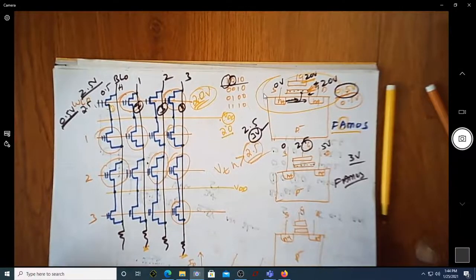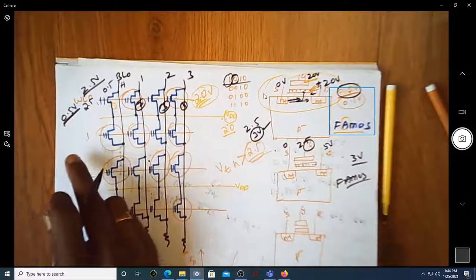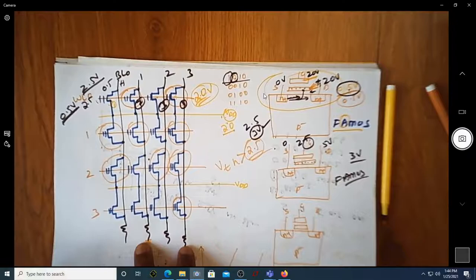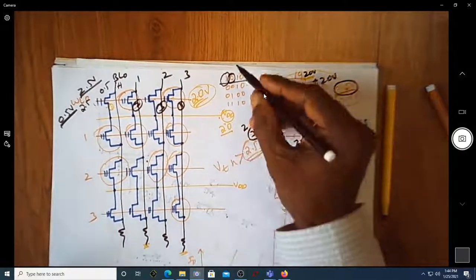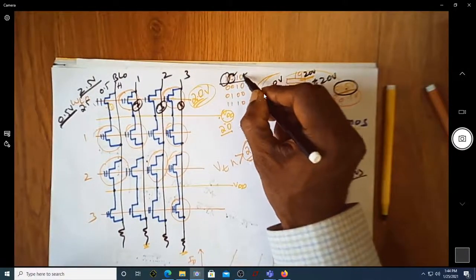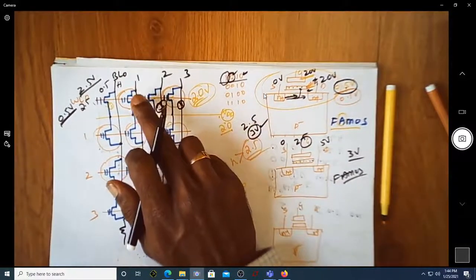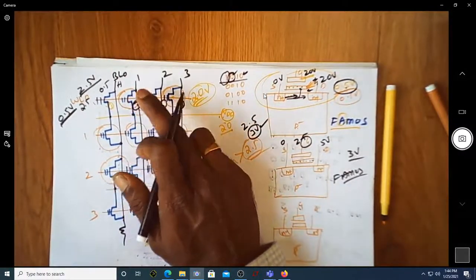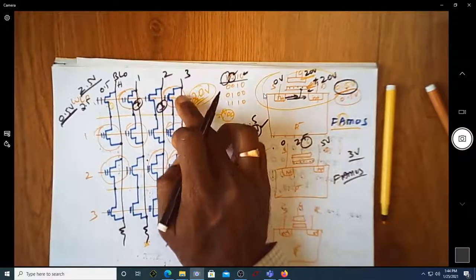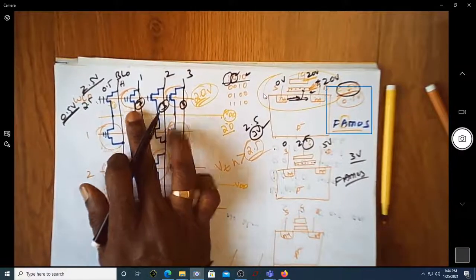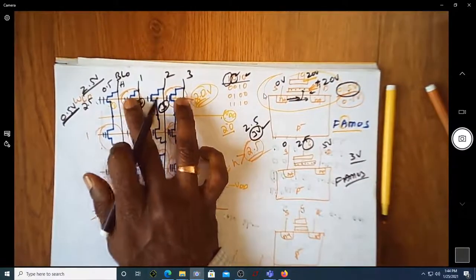2.5 volts. So after doing this setup of making this 20 volt, grounding only these two, why we are grounding only these two is because the corresponding columns of these two transistors are these two. So then this is going to certainly enhance the threshold voltage of transistor 2 and transistor 4. Similarly, we have enhanced the threshold voltage of these two transistors.